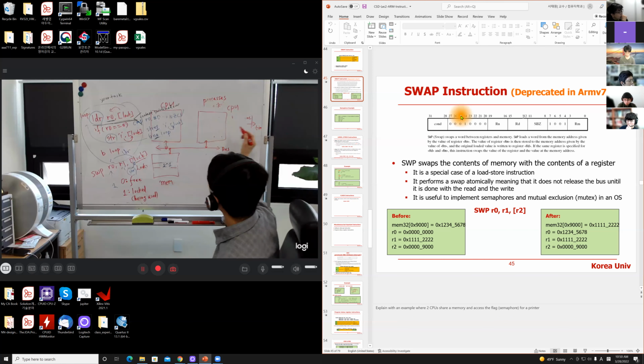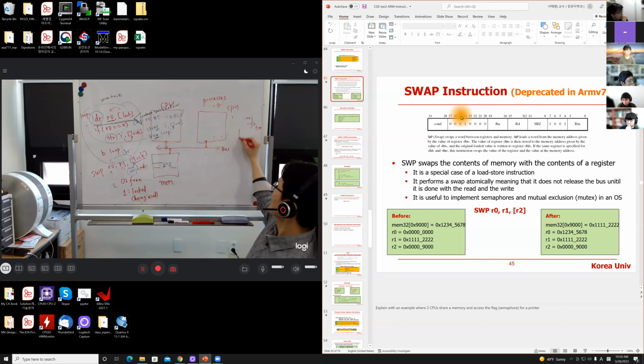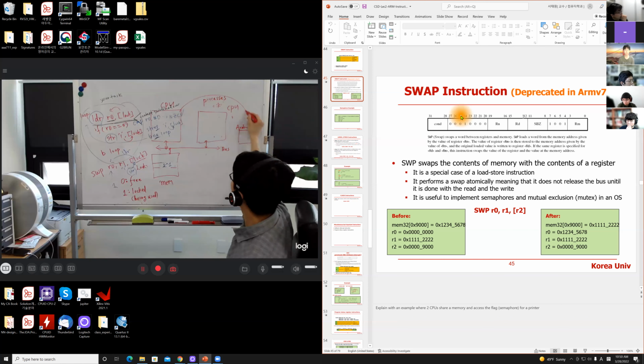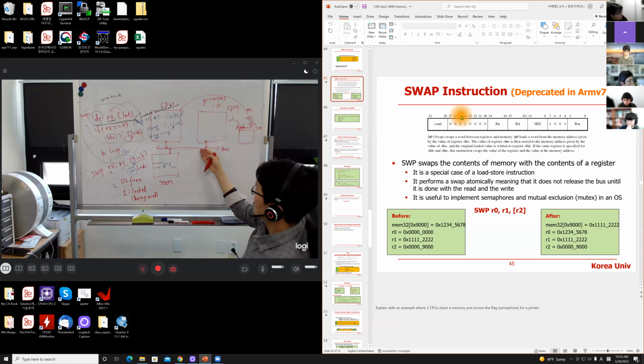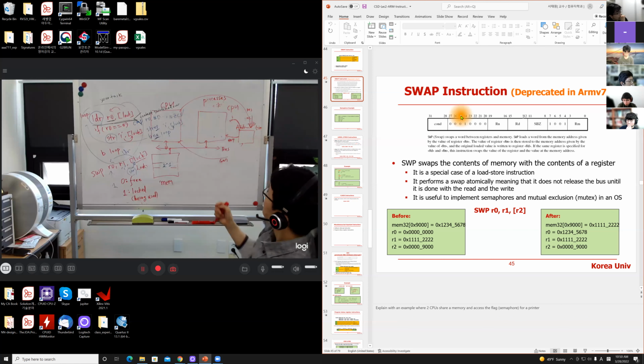So assuming that there is an arbiter, we have a hardware component called an arbiter. This guy is arbitrating this bus access. So there should be some connection from the CPU to here, a request: I want to use the bus to access memory. That is a request, and in response, this guy is sending a grant. This is a physical connection.